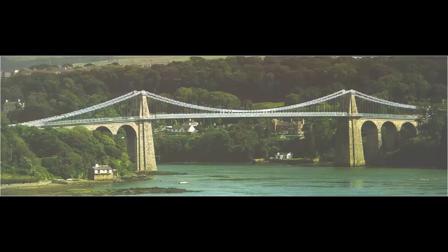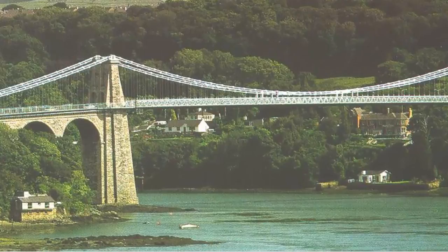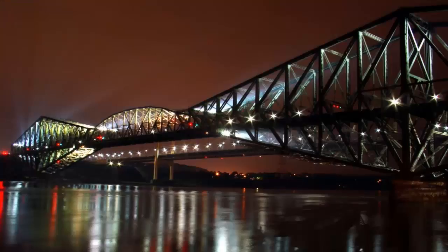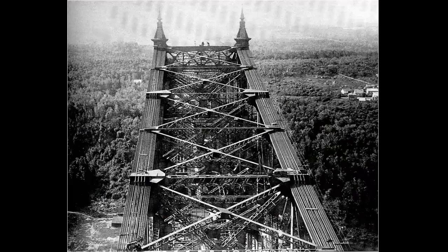The Menai Strait Bridge actually uses the equivalent of a huge bicycle chain. What looks like cables are actually chains made up of 9 feet long links connected by pins. This is the Quebec Bridge over the St. Lawrence Seaway. If you look closely at the 2 top chords, you can see that they are made up of over a dozen steel plates or links like in a chain that are then pinned at the truss nodes.